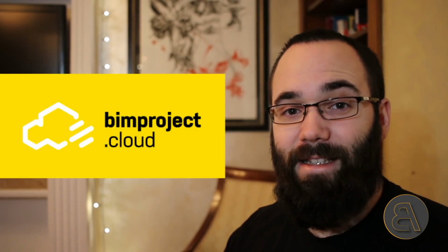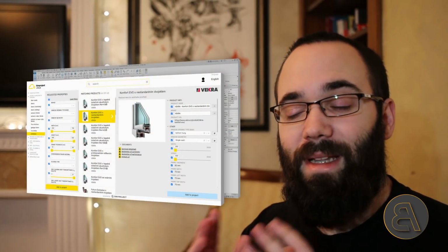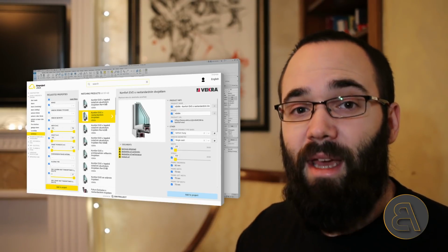So in this video, I'm going to be showing you an approach where you start off with the design. You kind of lay everything out, and then through multiple iterations, we're going to be loading in more and more data into our model. Now, to make this a little bit easier for us and to improve our process, I've teamed up with BIM Project Cloud, and this is a really useful plugin that allows you to, well, insert models into your Revit project, but you can really specify which type of model you want to use. You can update it, change the parameters, and feed more and more data with each iteration. So that's what I'm going to be showing you step by step inside of this video.